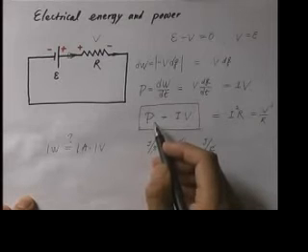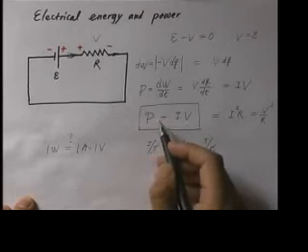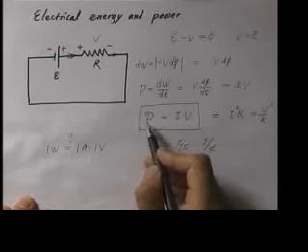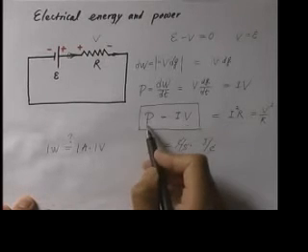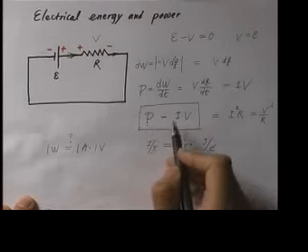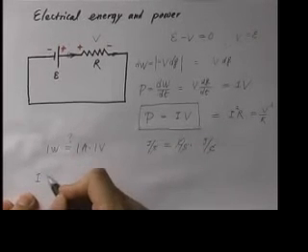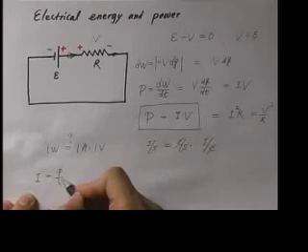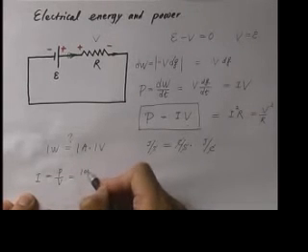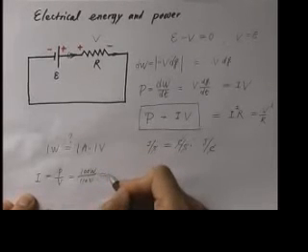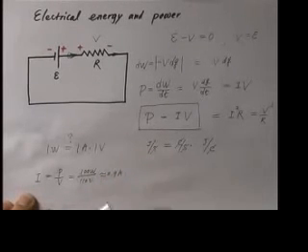Suppose it's 110 volts. This is the U.S. domestic power outlet, which is always 110 volts. This is 100 watts. You can then easily find the current going through a 100-watt light bulb. The current would be P over V, which is 100 watts over 110 volts, so it's about 0.9 amps. That's one thing you can do.